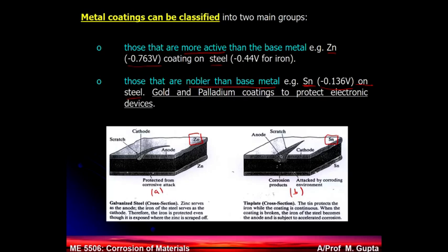Now let's go to the case number B here. You have tin, which is more positive electrode potential, and you have iron inside with more negative electrode potential comparatively. Which makes an anode? Iron or tin? Iron will make it. Will it corrode easily or badly?